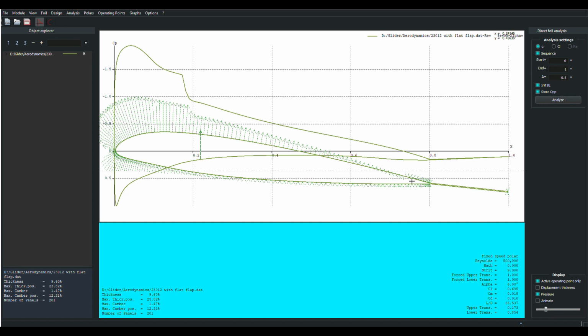We have the funny little reversal right here where we have a little bit of reflex in the airfoil. Pressure distribution is the same, and nothing happening back here on the flat plate except for some skin friction drag, and then right at the end of the flat plate we have two more pressure indicators here, and that's because the plate does have some thickness and the flow has to get around that sharp corner and get back to zero by the end of it.